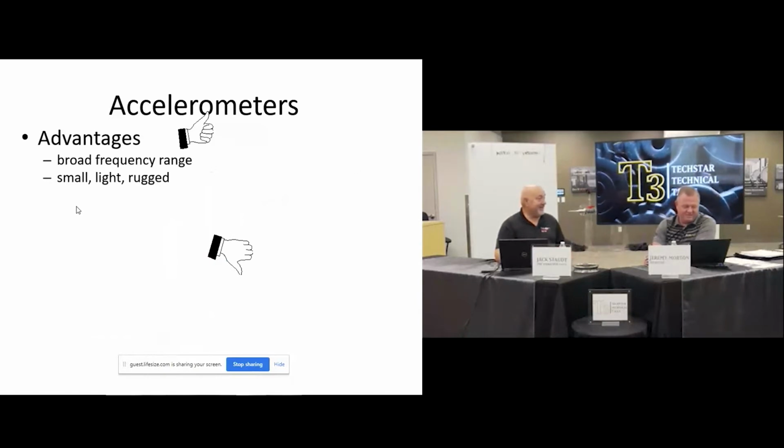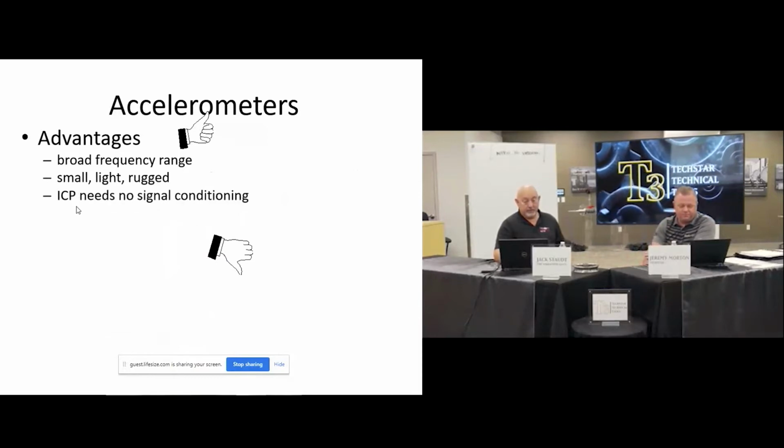Another consideration is the installation, how hard you torque them down. They have very specific torque ratings, and you don't want to just crank those things down because it's typically a preloaded piezoelectric crystal, and you can very easily crack those crystals. It may come in okay on your monitoring system, but it likely will throw off the vibration readings. It can either cause spikes or cause you to basically read a zero flat line. You just don't know which direction it's going to go.